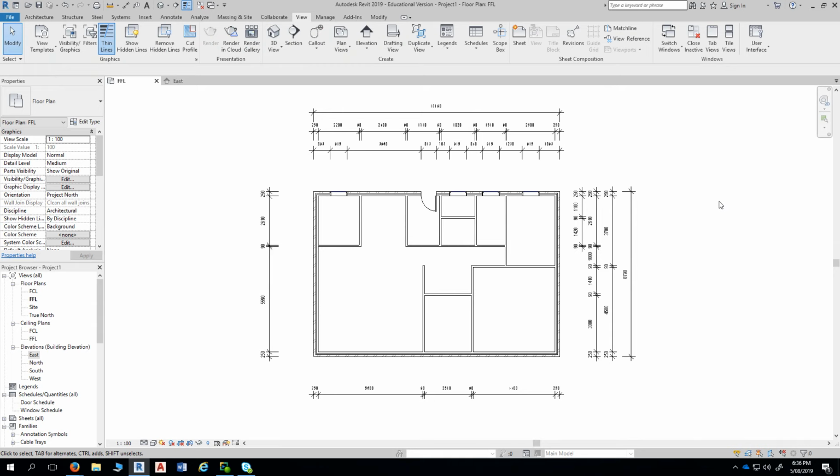Okay. So when you're drawing walls, try and draw them in the most efficient way that you can. Don't draw part walls, just draw the whole wall if you can. Look at the plan and think about the way that you would add the walls, and then start adding them in the most efficient way possible. All right. And again, don't worry about exact room sizes. You can sort that all out once you put your dimensioning around it. All right.